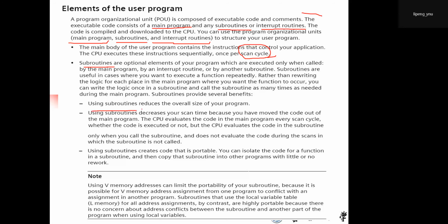Subroutines provide several benefits. Using subroutines reduces the overall size of your program. Using subroutines decreases your scan time because you move the code out of the main program.